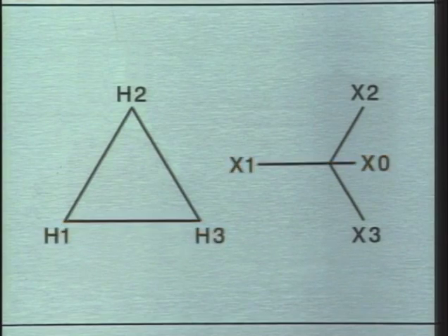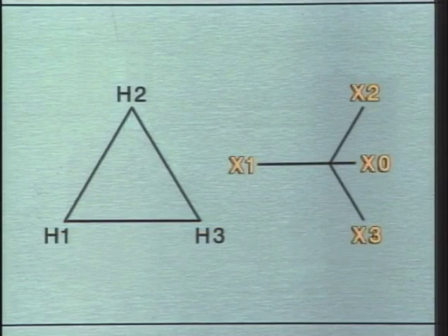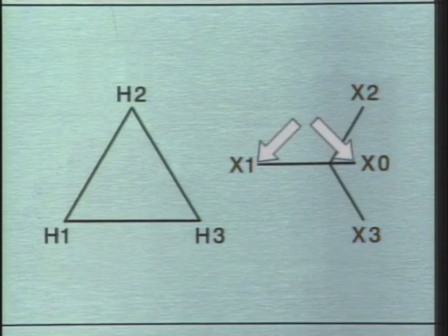When test connections are made, the exciting leads of the turns ratio test set are connected to the terminals of one of the lower voltage windings. For an example of the connection, the exciting leads are connected to the terminals X1 and X0.